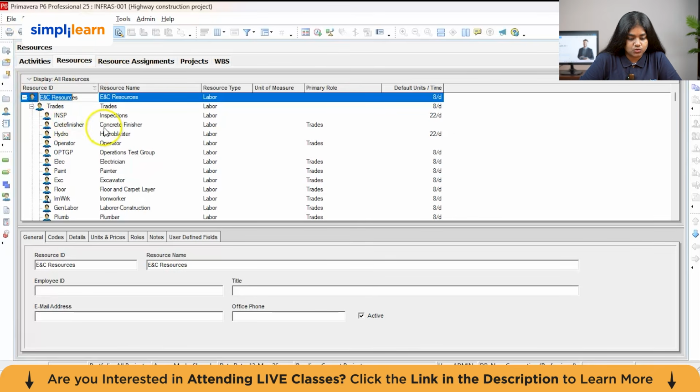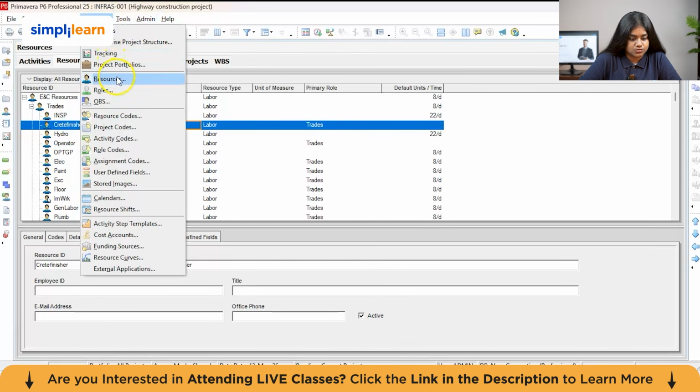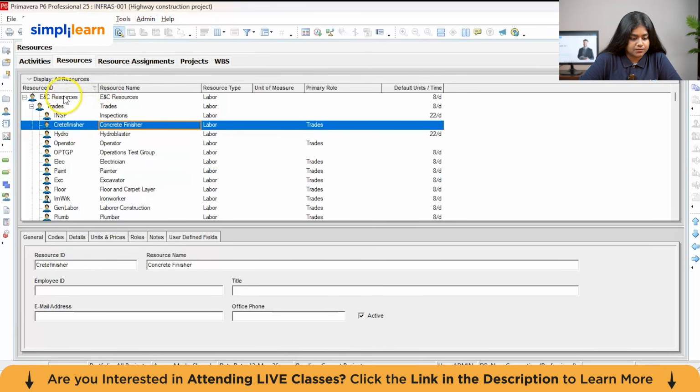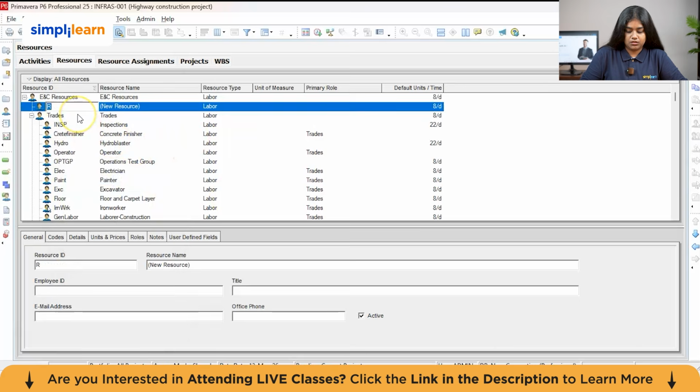So to create resources in P6, we have to go to Enterprise and then click on Resources and click on Add. Here you can add the resources. You can add a resource ID such as engineer.